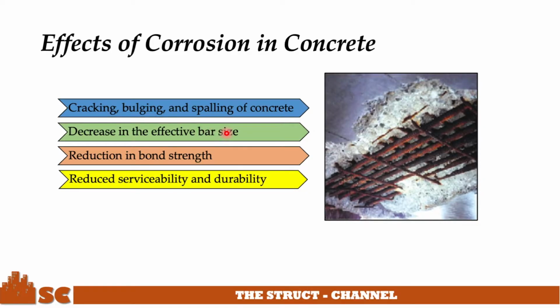When subjected to reinforcement corrosion, concrete structures experience delamination, in which the oxidized metal requires greater space causing wedge-like stress. Separation of concrete and reinforcing steel bars occurs when the force due to the stress surpasses the relatively weak tensile strength of concrete. Surface and internal cracks tend to develop in concrete and promote exposure of reinforcements to corrosion. This, in turn, imparts an excessive reduction in the bond strength, characterized by the adhesion and slippage resistance between steel and the enveloping concrete. With all these effects, this in turn may reduce the serviceability and durability of the structure.